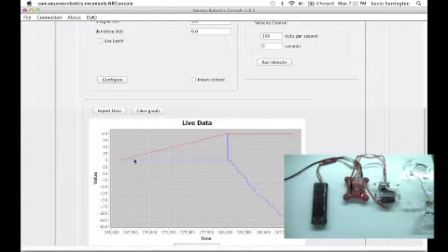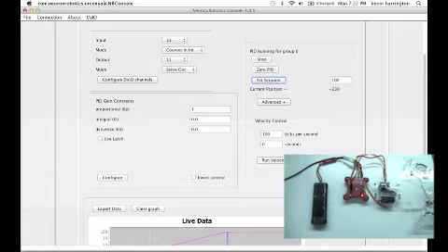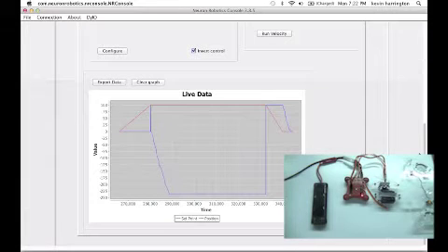You'll notice that the PID controller is what's called divergent. The set point went up, but the motor sent the value spiraling downwards. There's a configuration for this, and this is what's called the invert control. Check the checkbox and configure your DyIO again, and try setting a new set point. You'll notice now that the controller is convergent.